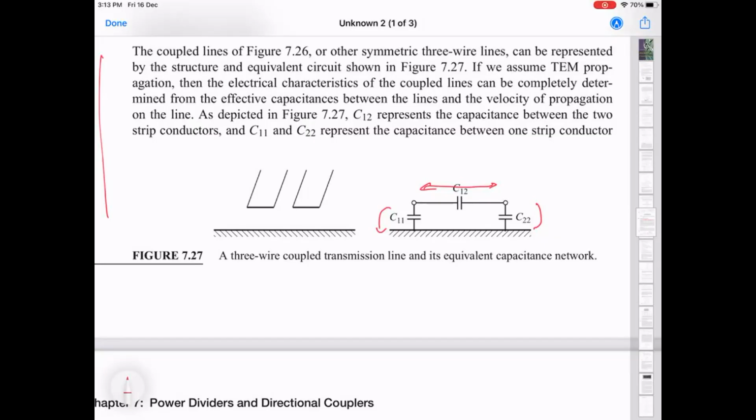So here also, you end up with the same kind of two modes. Earlier you would say that there is some voltage V1 and some voltage V2 with respect to ground. But you can now talk about things like V1 plus V2 and V1 minus V2, right, in general. And again, if you go back to our previous discussions on this even odd mode analysis, this is like the even mode system, and this is like the odd mode system. So this way of thinking about it, like thinking about this intercapacitance, allows us to figure out what we mean by those modes when we try to calculate.